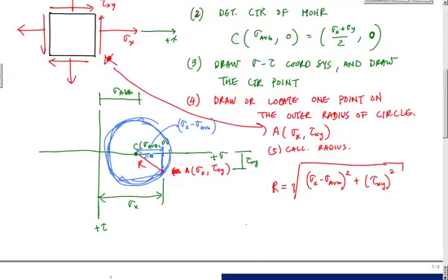Okay, and look at this. The maximum normal stress is this point right here, and the minimum would be this one right here. These two endpoints are our principal stresses, sigma 1 and sigma 2, and then our maximum shear stresses would be up here or down here. This would be tau max. Sigma 1 being the maximum principal stress.